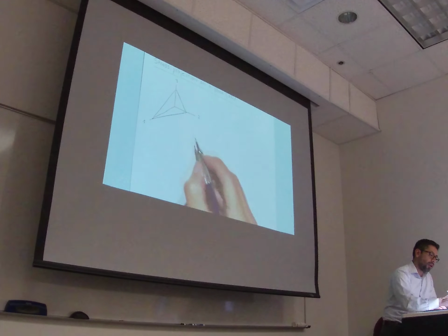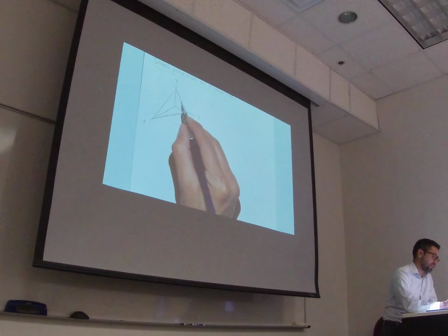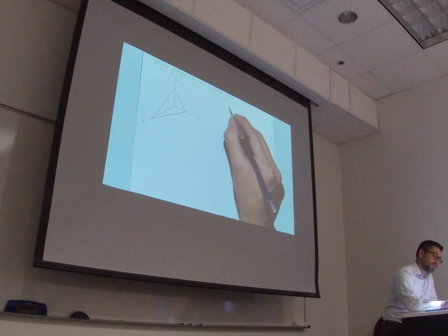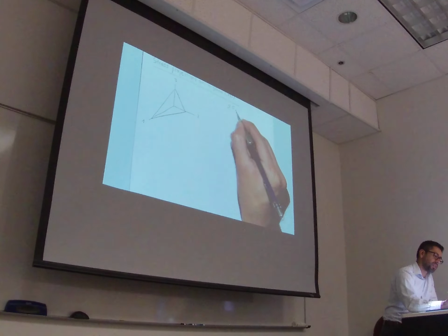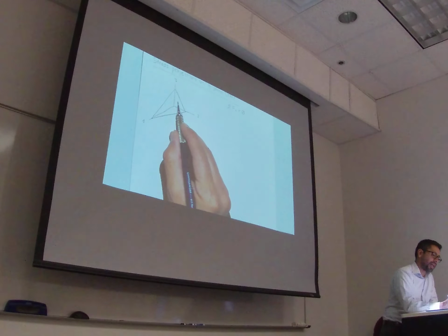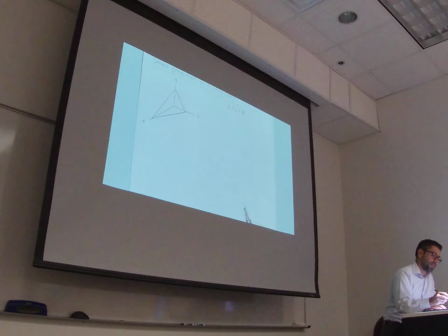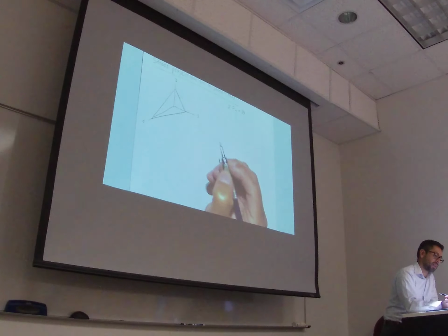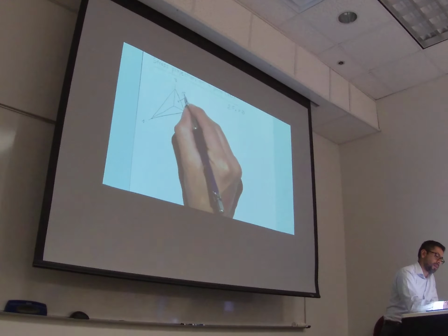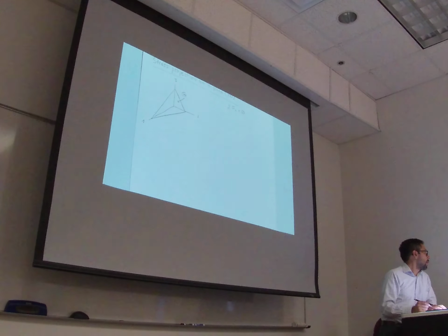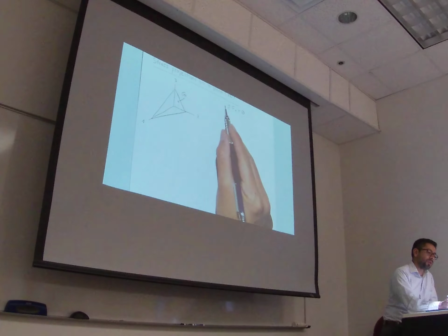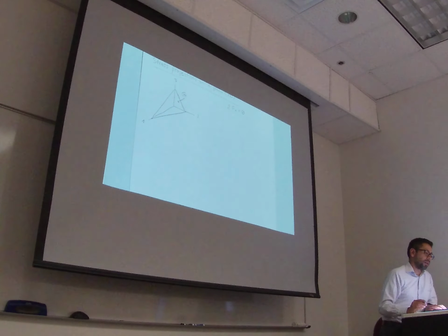So normal to face number 1, which is this one, perpendicular to axis number 1, if I want to do the summation of forces in direction 1 equal to 0, what is going to be the stress acting on face number 1, in direction 1? It's going to be sigma 1,1. There is also sigma 1,2 and sigma 1,3, but I don't care about that because I'm just doing equilibrium now in direction 1.